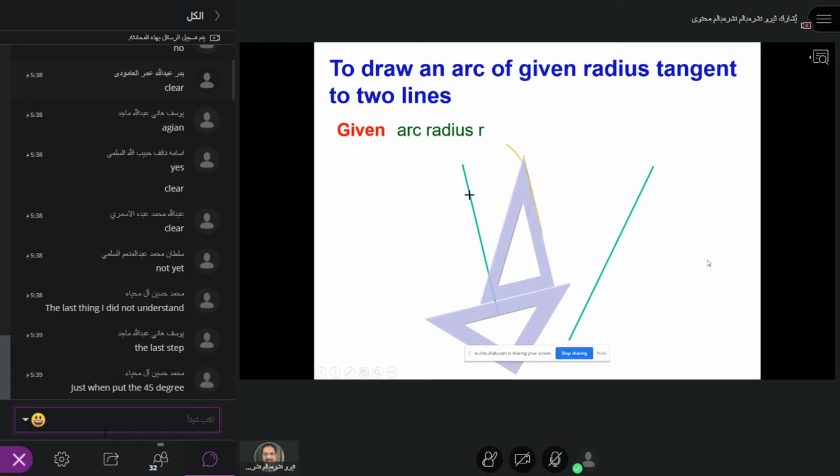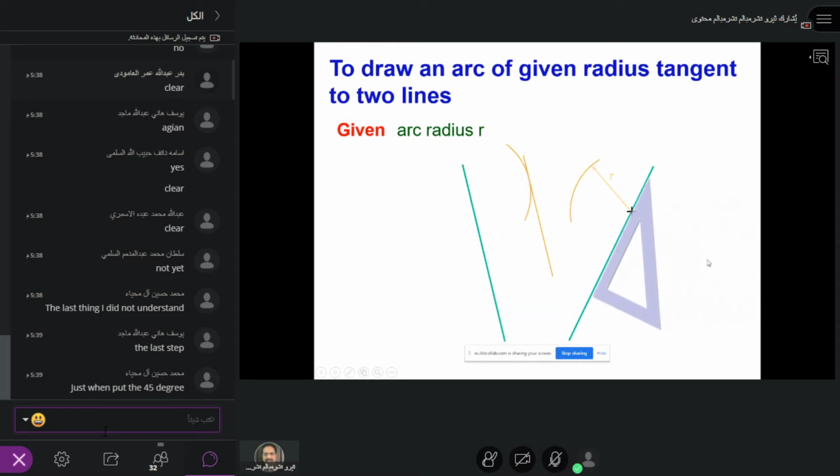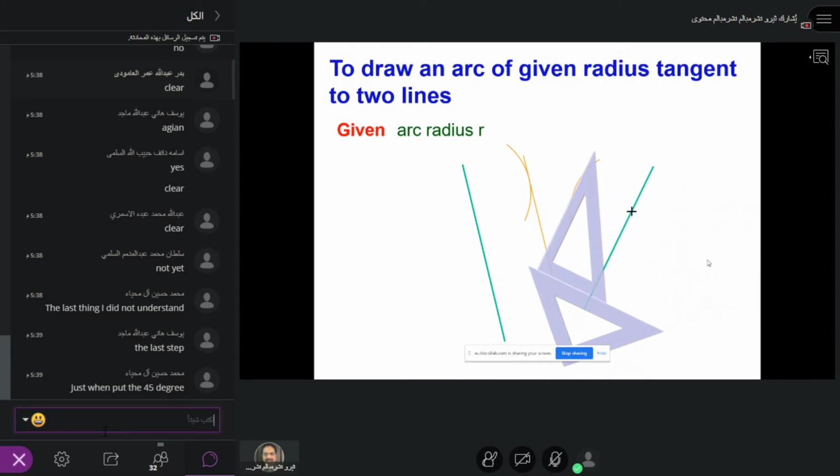Then use the same method and draw the other line, move it forward, and then draw the radius. And from the arc, you draw the tangent and join it there. Now, these both points are joining here. Now you have to start drawing the perpendicular line from, because initially this is the tangent. This is the tangent.